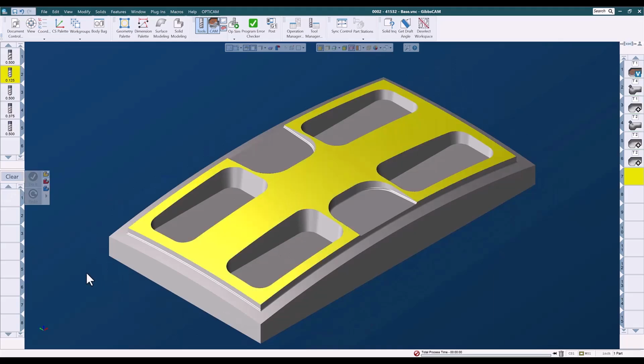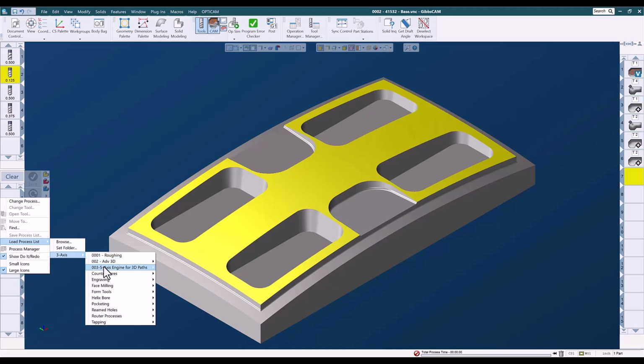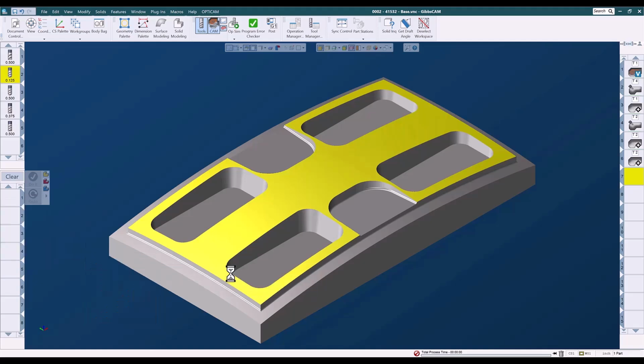So I think next we will deal with the top surface here. Let's find something for that. I'm thinking probably a geodesic, maybe offset from multiple curves, and it should be able to pick those up automatically. So let's right click, and I'm pretty sure I've got one of those. So we're going to go to 5-axis, geodesic, and parallel to multiple curves, automatic with a, that's 1/2 inch end mill. That's not going to work. Let's go with a 1/2 inch ball mill.